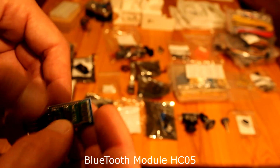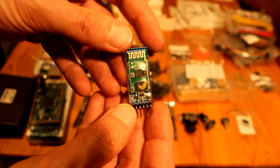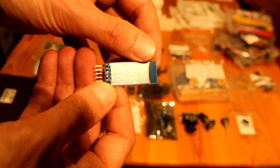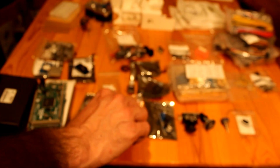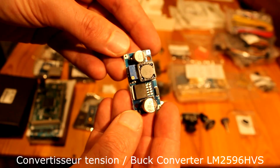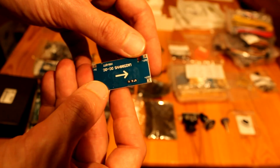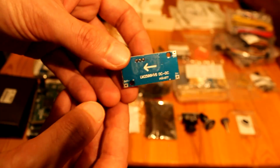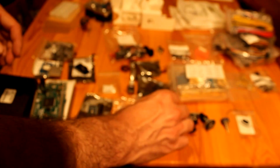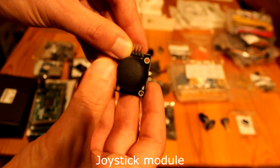We continue with the Bluetooth module. This part is very interesting because you access all the catalogs inside Stellarium or Sky Safari software, so you can go to any object of the NGC catalog, for example. This is a buck converter. This is a voltage converter. For example, you have a 12 volt input and you can adjust the output voltage. For us, we're going to set it at 5 volts because the Arduino Due does not have enough power to supply all the parts that need 5 volts. This is the joystick module for Arduino.